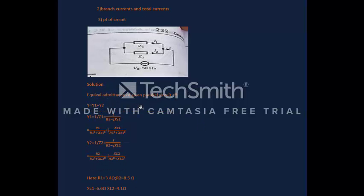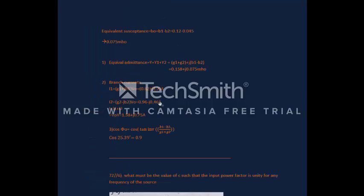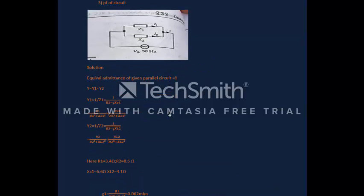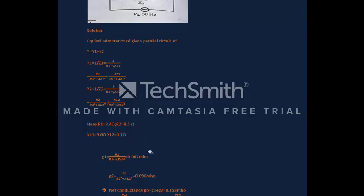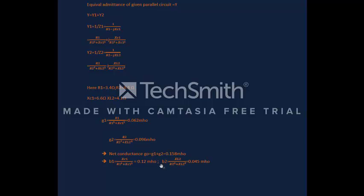Equivalent admittance of the given parallel circuit is Y. Y is equal to Y1 plus Y2, which is nothing but admittance 1 plus admittance 2. Y1 is equal to 1 upon Z1, as we have already seen. Y2 is also the same. Here R1, R2, all the given values, we find out using this equation, which is G1 is equal to R1 by R1 square plus XC1 square, comes out to be 0.062 mho, and G2 comes out to be 0.096 mho. The net conductance G0 is equal to G1 plus G2 is equal to 0.158 mho.